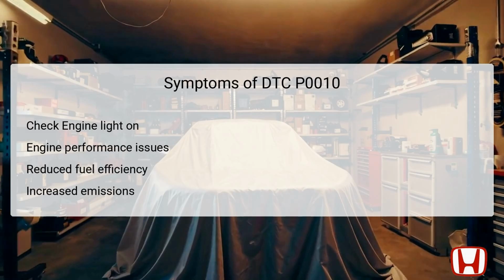Identifying the symptoms associated with DTC P0010 is essential for diagnosis. The most immediate indicator is the illumination of the check engine light on the dashboard, signaling a malfunction within the engine management system. Drivers might also experience noticeable performance issues, such as poor acceleration or rough idling, as the malfunctioning solenoid impairs proper valve timing.